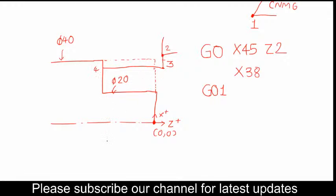Since we start cutting, we have to move the tool from that location to the 4th point, and this depth is 15 mm. So what should we write? G01. Once we start cutting, we should reduce the speed, because at 24,000 mm per minute we should not cut. So we will be lowering the feed rate, and since it is a rough cut, I will be putting a little bit higher feed rate. So G01.